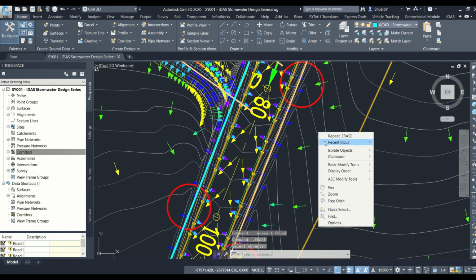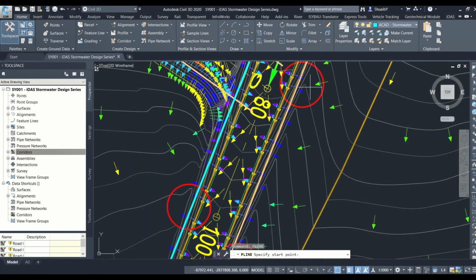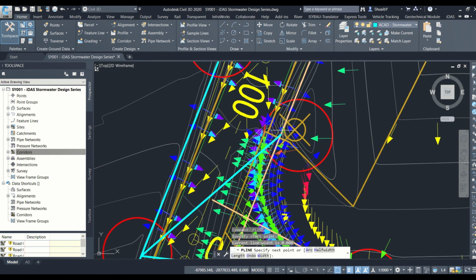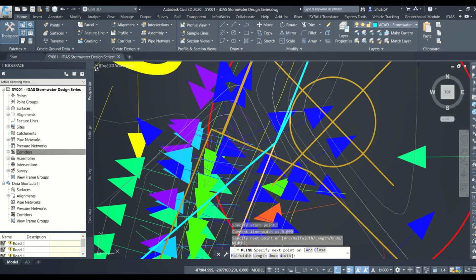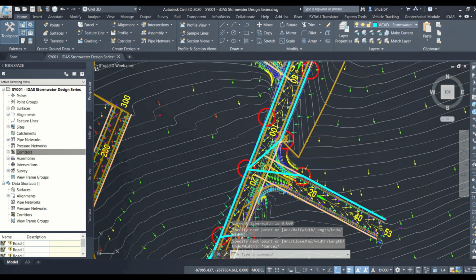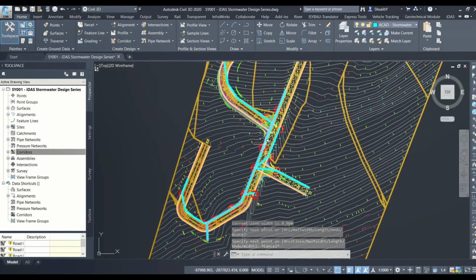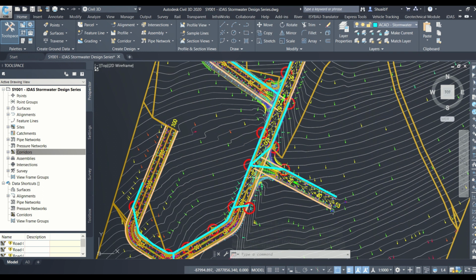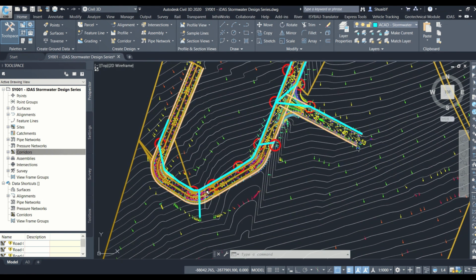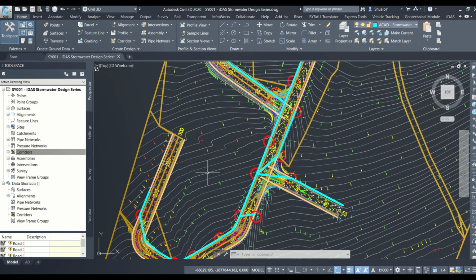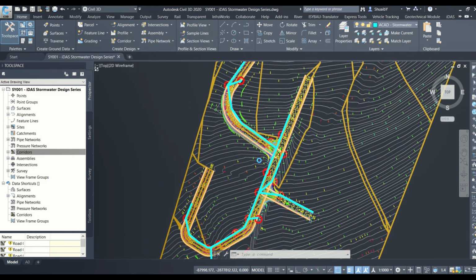Again, you see I did erase that one because it's a small segment. It doesn't make a problem, to show you that you can erase it as well. So I'm also displaying the basic functionalities that are built in. It's not rigid anymore, so that'll be fine. Also, in practice, you would like your low point to be at the correct position relative to your road so that the water all drains to that point before reaching the road. So I think we're good. I think we are more or less done. Let's just have an overlook.